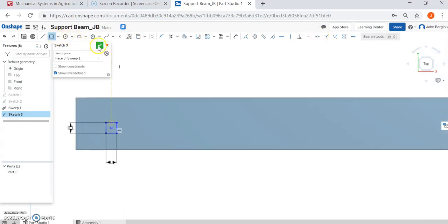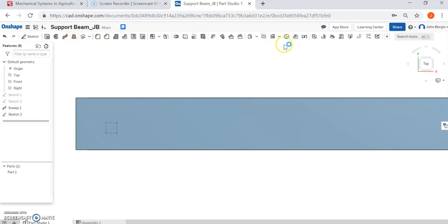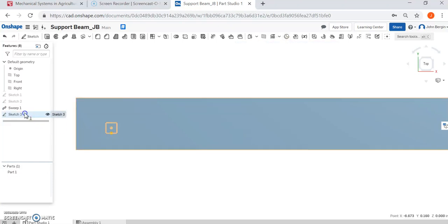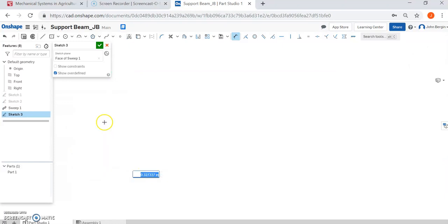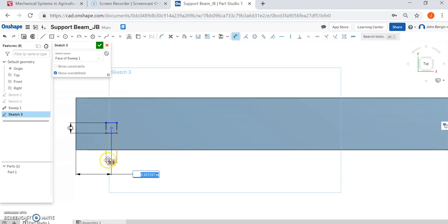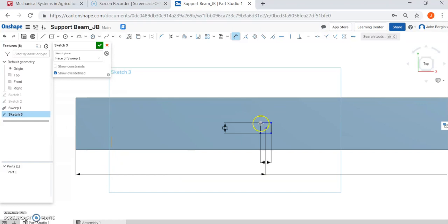Next, we need to place it in a pretty precise spot here. So opening back up that sketch toolpath, I have the dimensioning tool. I can put it exactly where I want it. So I'm going to go from center of the square. You can see I'm at the center right here, not at the edge where that line is, at 1.75 inches. And then I want the top to be 0.2.